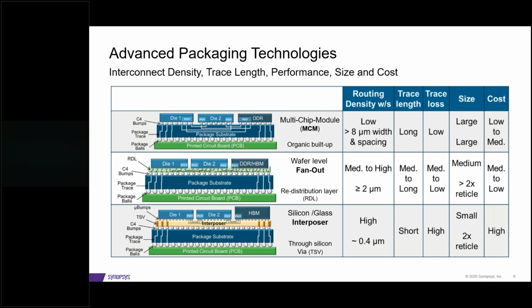So if I would categorize them, and I can be challenged that there are a lot more types of packaging solutions out there, but if I could bucket them into three major device structure technologies, I would break them down into the traditional multi-chip module, MCMs, that are typically today built off of the organic substrate. This is the very light green layers on the bottom of these structures.